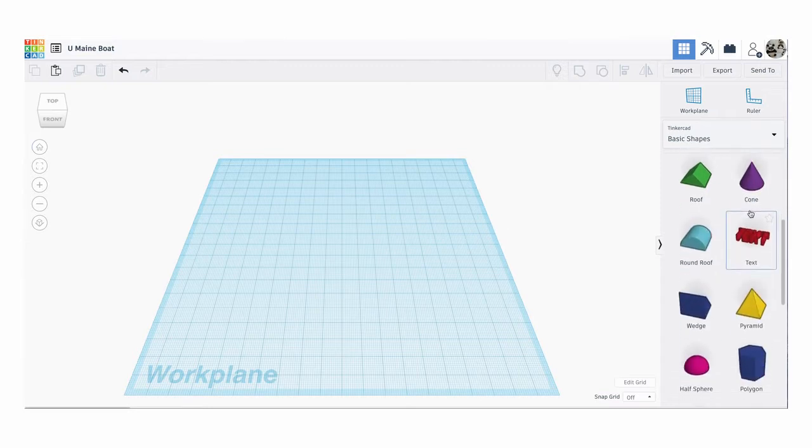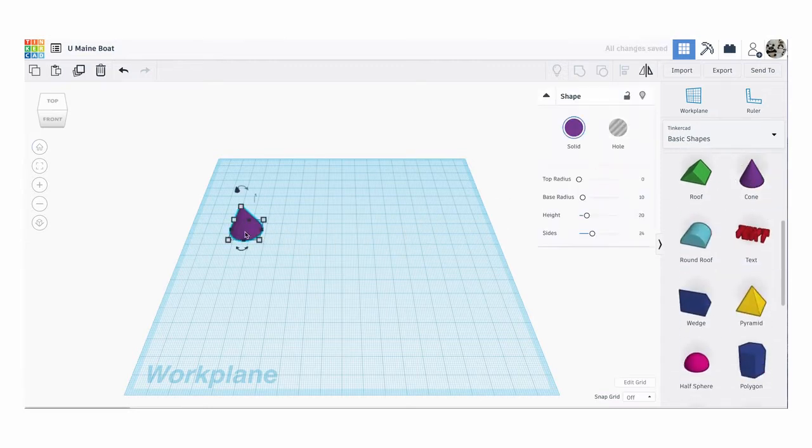We will start with the first shape, the purple cone located below in Basic Shapes. Change the size to 5. You can slide or type 5 in the drop-down box. Go in this order to avoid confusion later. Change all the dimensions to 30, including the height. To change the height, click the middle white button.